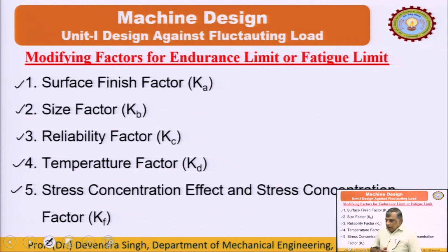And then finally, there are a number of applications in mechanical engineering where we need to make components with an abrupt change in the cross section. We need to provide some holes. So, we need some arrangements for assembly purpose. So, the area abruptly changes at a particular section. That invites a high level of stresses, that is called the stress concentration effect. And to incorporate this in our design against dynamic load, the stress concentration factor will be included in our design.